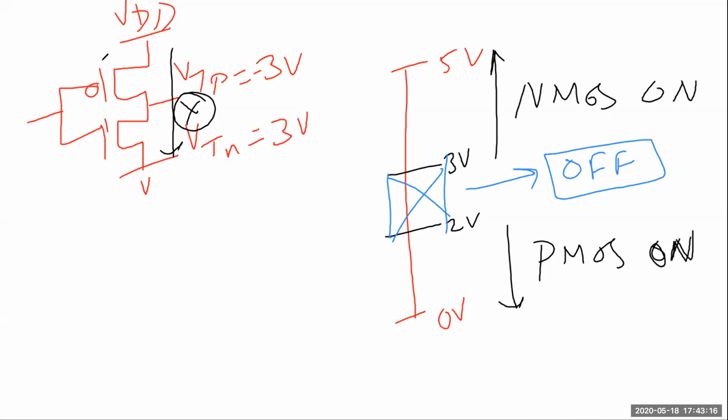So it's just dynamic power, like you're saying. So for the static characteristic, I guess this will be interesting. I've never tried a high VT device, but if you do a noise margin, it'll be interesting to see how the noise margin looks. So for this one, I think your noise margin will be higher than the supply voltage.